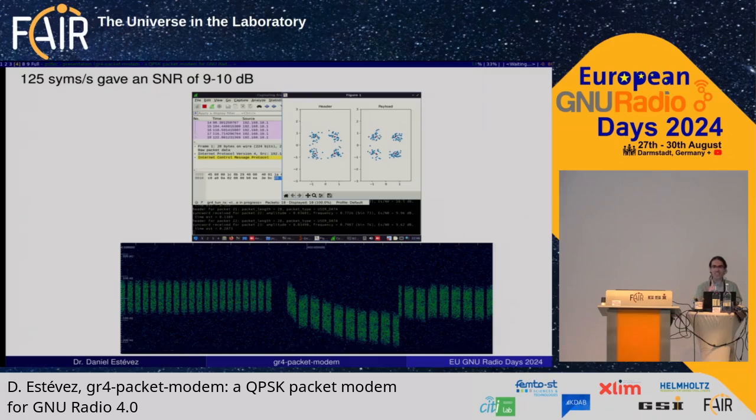And then the interesting thing is this is 5.9 gigahertz with this USRP, no GPSDO, no nothing. So the frequency oscillates like crazy, and I needed to tweak all the Costas loop parameters. But it worked great. I was testing at night and, you know, change, recompile, run, and it ran. I will put up the SigMF file of this probably this afternoon for all of you to play with. And that's all I had.